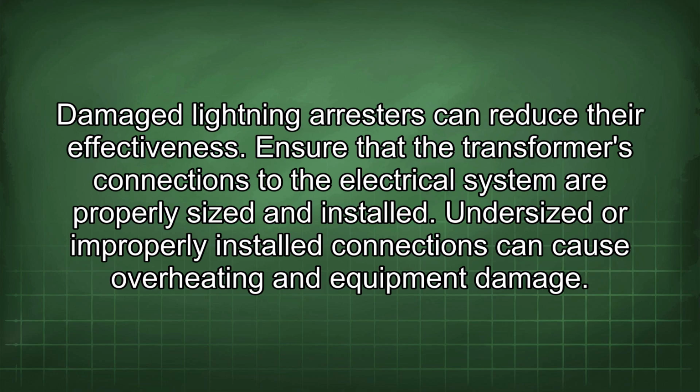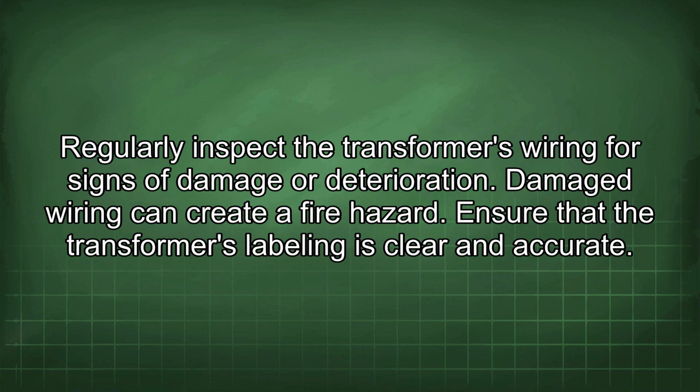Ensure that the transformer's connections to the electrical system are properly sized and installed. Undersized or improperly installed connections can cause overheating and equipment damage. Regularly inspect the transformer's wiring for signs of damage or deterioration. Damaged wiring can create a fire hazard.